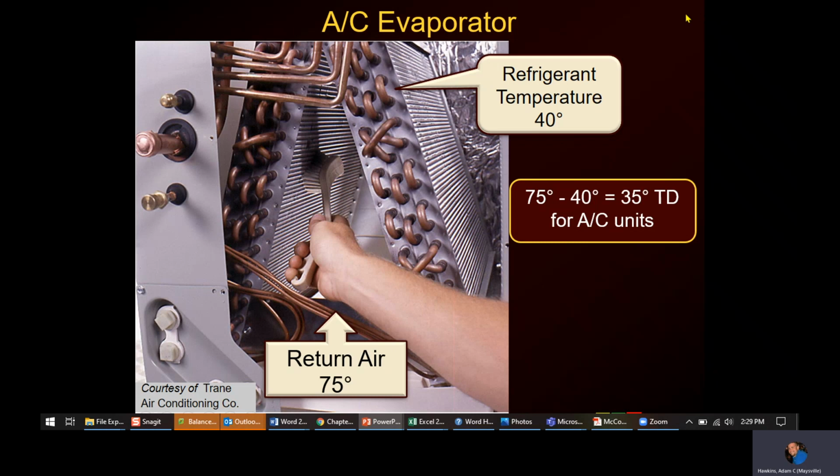It also makes a difference here, where you see that they're actually cleaning that evaporator. First of all, you're not going to see what they're seeing without taking the cover off. Usually there's a little metal triangle on the front of these coils. If you do see it without taking that cover off, that's an issue in and of itself. The air has to be forced, pulled through that coil, so there can't be a way for it to get around it. With that triangle being out, obviously it's going to be able to get around it.